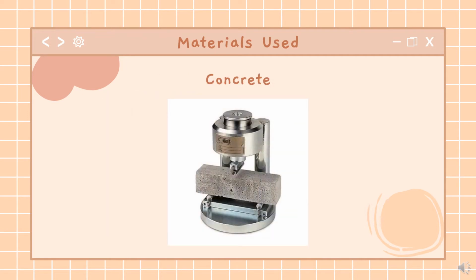When a 3-point bend test is done on a brittle material like ceramic or concrete, flexural strength is often called modulus of rupture. This test provides flex strength data only, not stiffness. The 4-point test can also be used on brittle materials, though alignment of the support and loading anvils is critical in these cases, and the test fixture for these materials usually has self-aligning anvils.